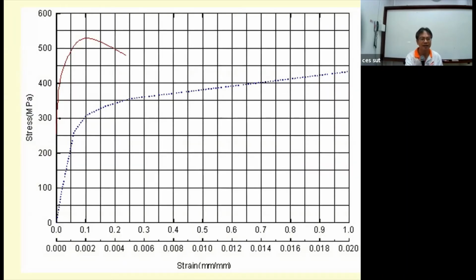On the diagram, 385.8. This is 300. This is 400. And this is going to be 375. So we may have the point about here and we project it. And then we have the strain following this of 0.0108, for the strain of the bottom portion of the column.